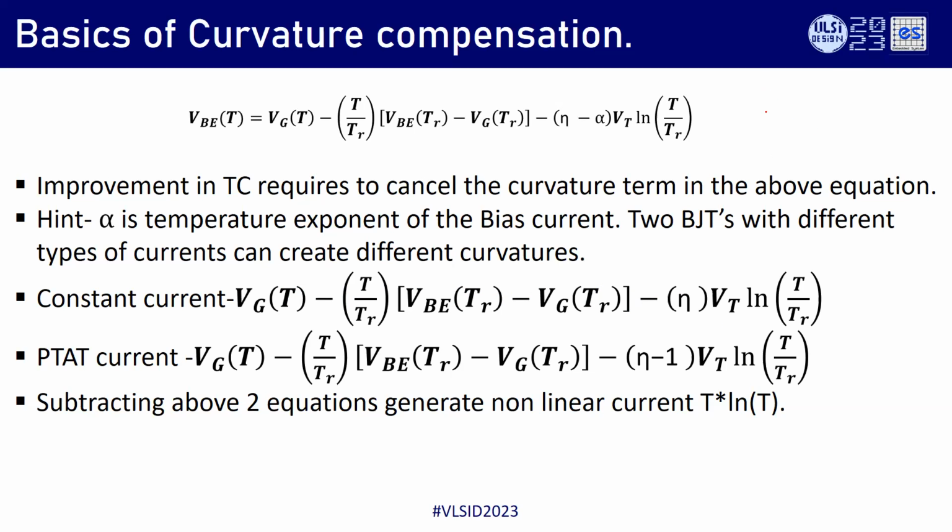Just to give a recap, this is how they assume the VBE is changing, and this is PTAT. PTAT is pretty linear. That's one of the most linear and predictable parameters I have seen in my life. The hand calculated one and the simulated one match very closely compared to the other parameters, whereas the VBE will have a curve like this. So we are assuming it is linear and compensating, which means we are leaving out this curvature, and that will give the curvature error.